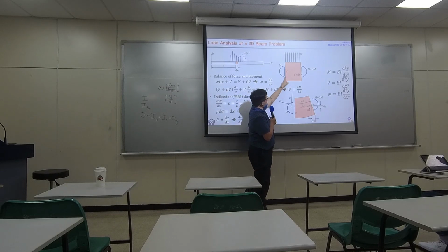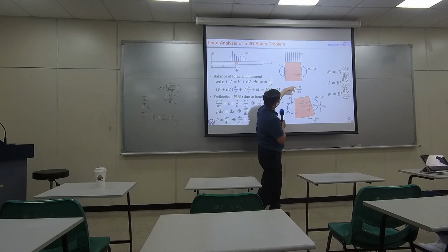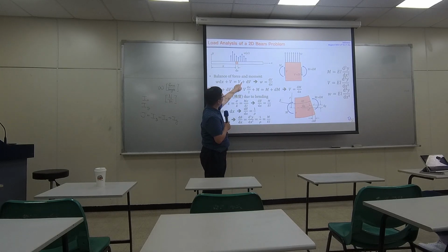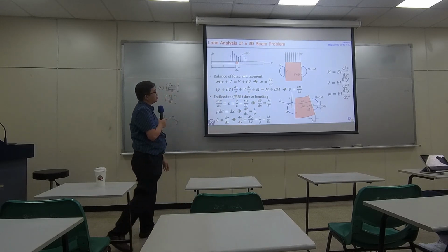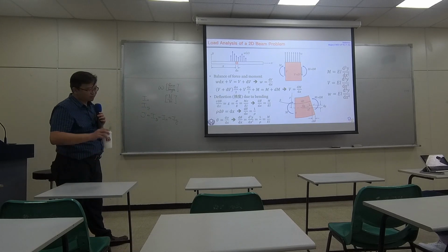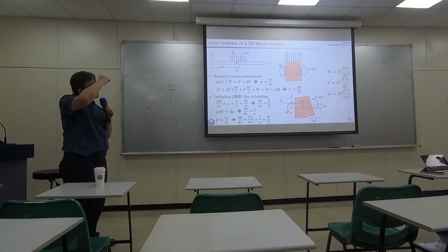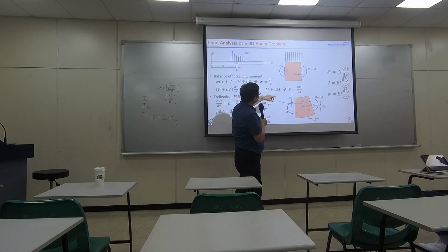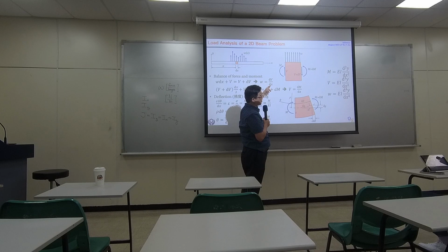Adding the upward V equals the downward V plus dV. And as you can see, these two V cross out. At the end, you have W equals dV over dx. So what's interesting is that if there exists some distributed load on the top, that will generate some increment of the shearing force.